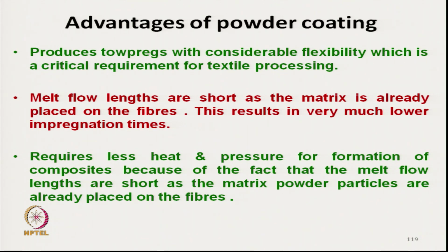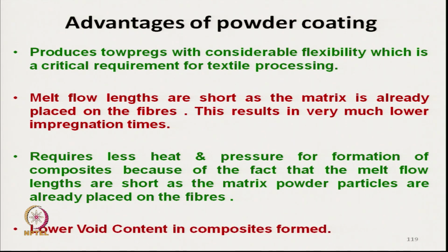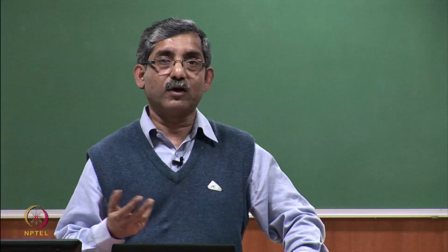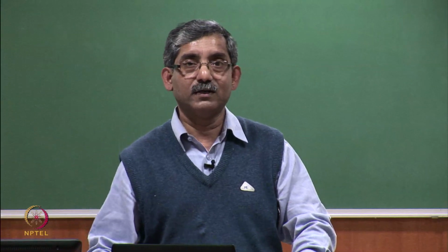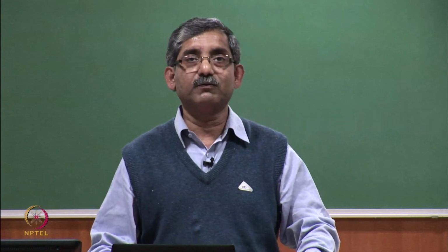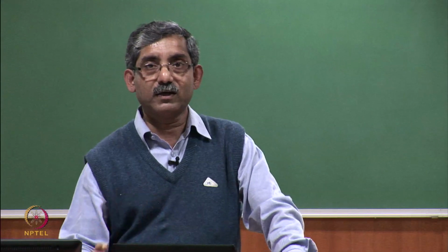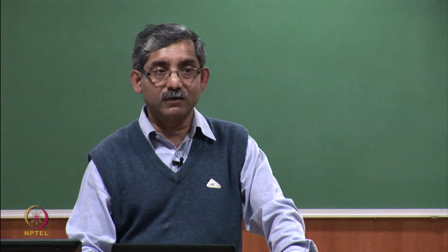It again requires less heat and pressure for formation of the composite, and the most important thing is that this results in very low void content of the composite. In other hybrid yarns, there are chances of higher void content due to non-uniform distribution of matrix fiber, but here the chances of void content are least.